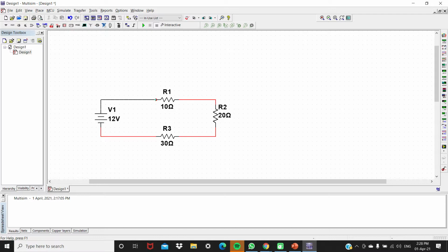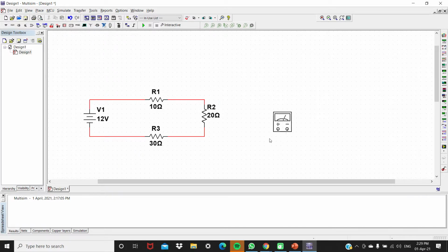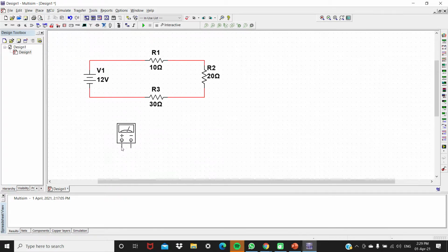Okay, so connect back that node. Now remember, when we had our first class, I was saying that these are series resistors. It is all connected side to side, so we can simplify and get the total equivalent resistance by adding up all the resistances. So it should be 30 plus 20 plus 10, so it should be 60 ohm.